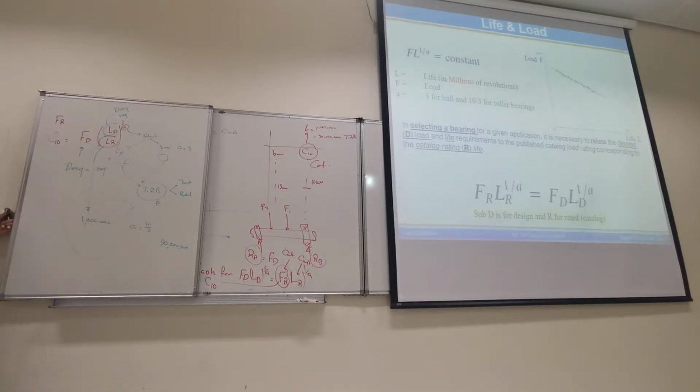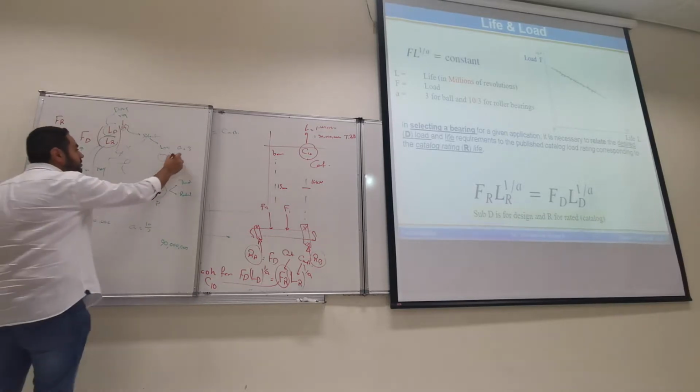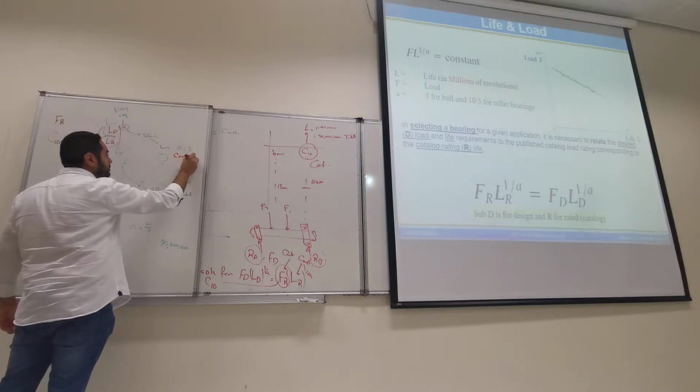Now you can search in the catalog for the right bearing. In the selection of A, the difference between cylindrical, ball and tapered is in their application. A ball bearing can carry combined load, but its thrust load capacity is poor.